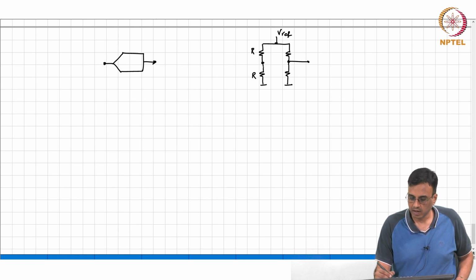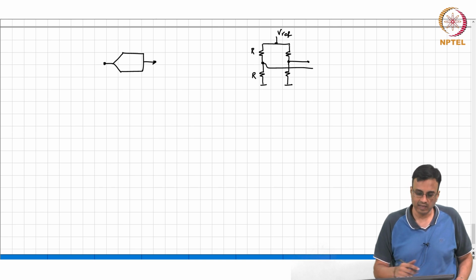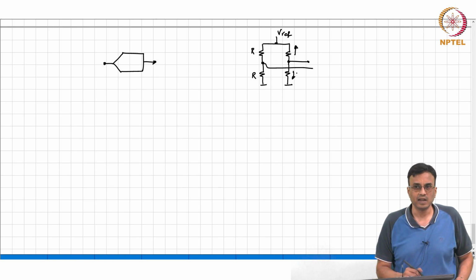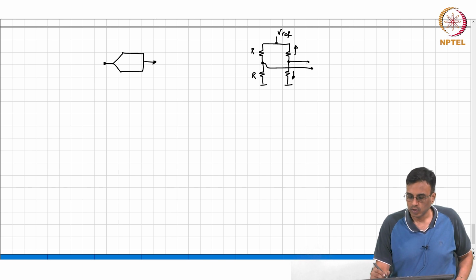You are standing on the weigh scale, and the way the sensor is built is that if you stand on the weigh scale, this resistance increases with weight and this resistor decreases with weight. If no weight is put, then these two are exactly identical.